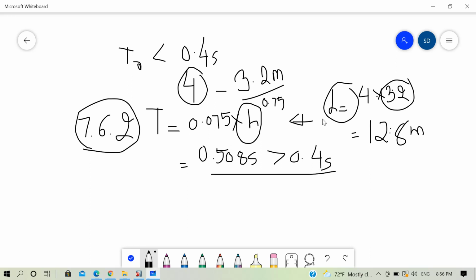So we have to use the linear dynamic analysis method. Remember this clause also, 6.4.3 of IS 1893-2016 states that the equivalent static method can be used for those structures with approximate natural period less than 0.4 second. When we calculated the time period of our building, we got it to be more than 0.4 second. So in this case, we have to perform the linear dynamic analysis method.